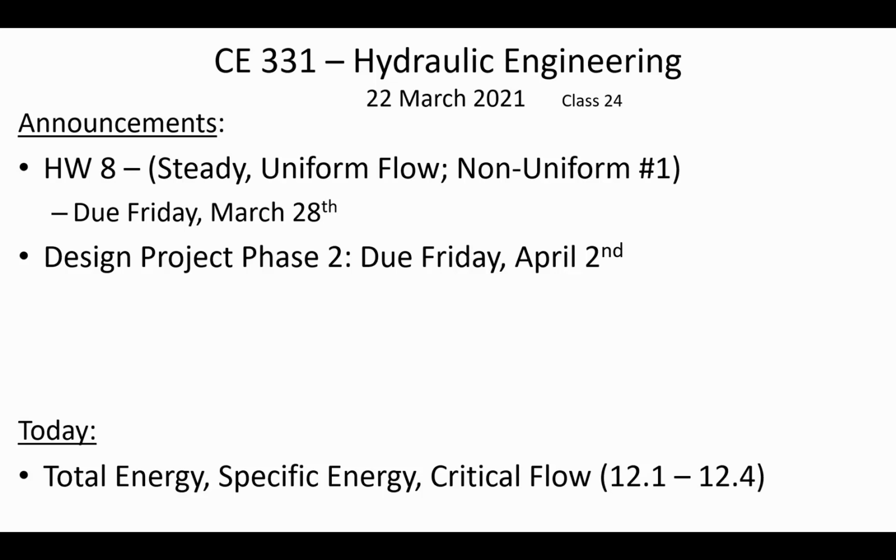I've been working on an example over the weekend that I'm going to take the time to record and illustrate how you could solve a network using the loop method and Hardy-Cross approach with a spreadsheet, and then get the same flow values if you solve that using EPANet. So I'll send you the link, and I'll also post that on Blackboard later this afternoon so that you can get started on phase 2, which is pipe network optimization.